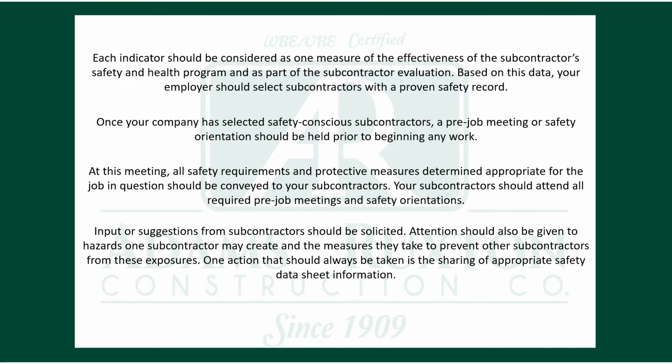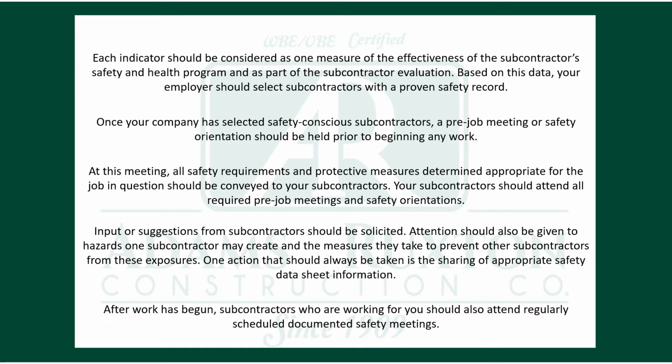Attention should also be given to hazards one subcontractor may create and the measures they take to prevent other subcontractors from these exposures. One action that should always be taken is the sharing of appropriate safety data sheet information. After work has begun, subcontractors who are working for you should also attend regularly scheduled documented safety meetings.